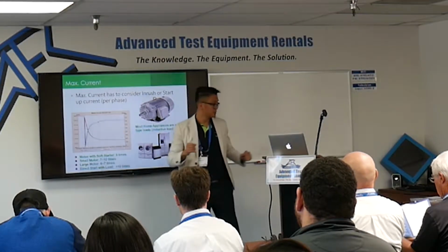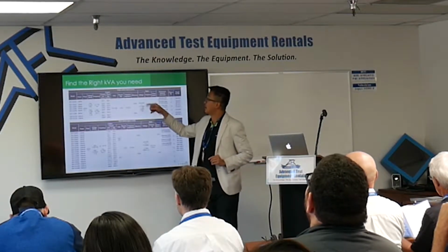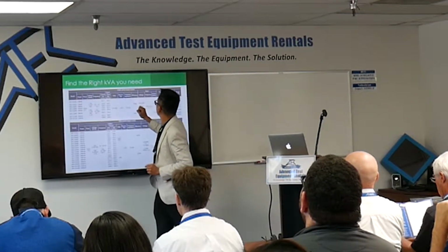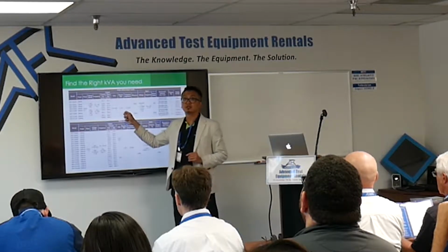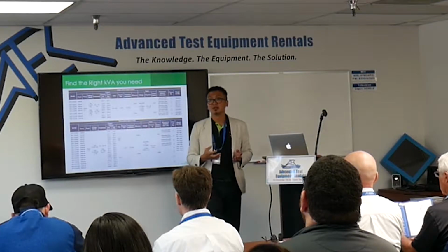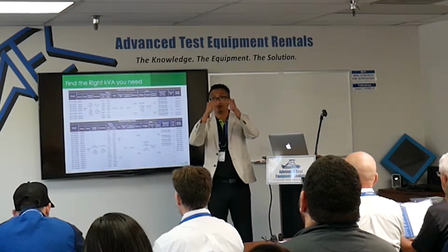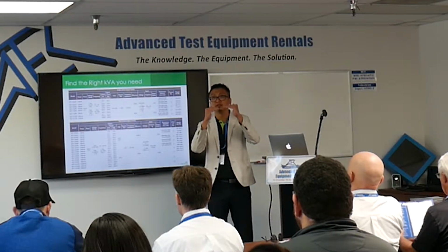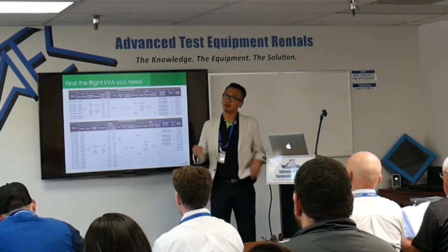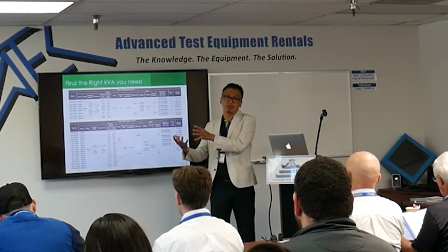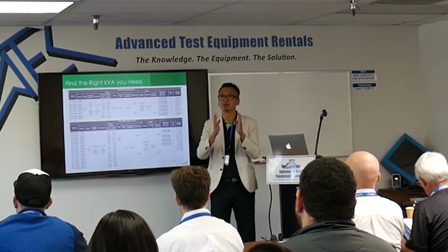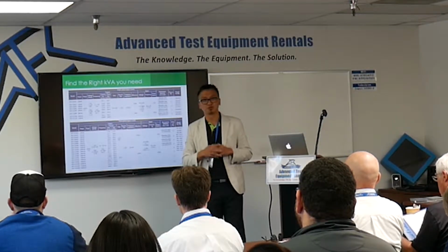When you see the spec of the power supply, you will usually see the regulation rate. For example, this one shows 1%, which means it can regulate the voltage within 1% in response to the load. But you have to make sure it doesn't trip. If the current is over what your power supply can handle, your power supply will trip.